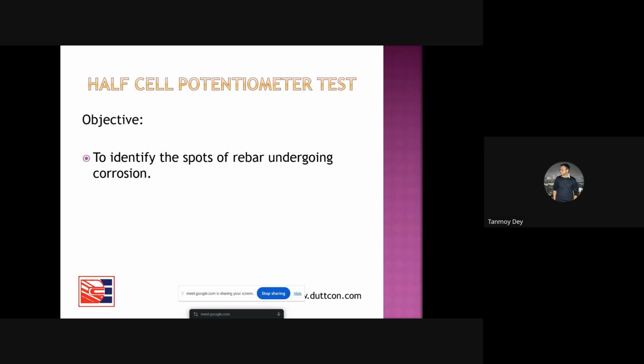That's why corrosion matters. I think in most of your houses, wherever there is a bathroom or washroom, the column below it gets cracks, because the TMT bar inside is more susceptible to corrosion.